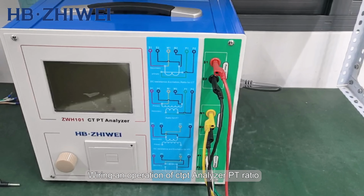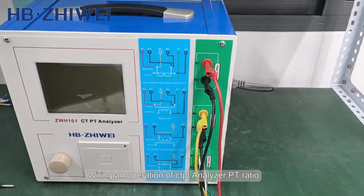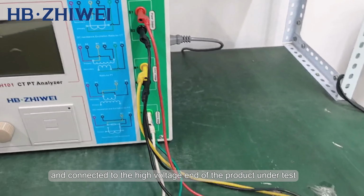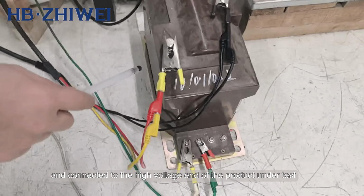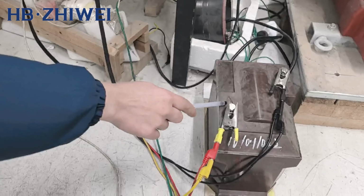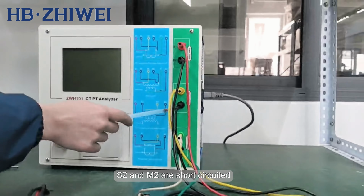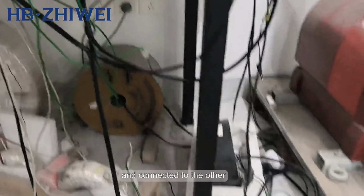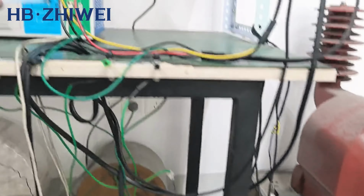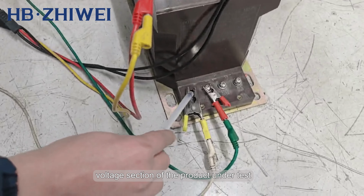Wiring and operation of CT-PT analyzer PT ratio. S1 and M1 are short-circuited and connected to the high-voltage end of the product under test. S2 and M2 are short-circuited and connected to the other side of the high-voltage terminal of the product under test. P1 and P2 are connected to the low-voltage section of the product under test.